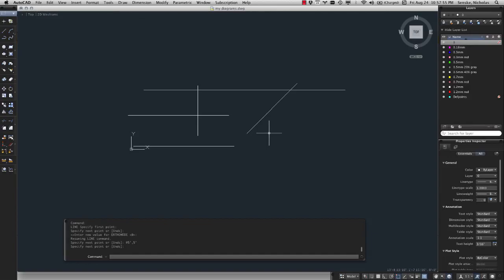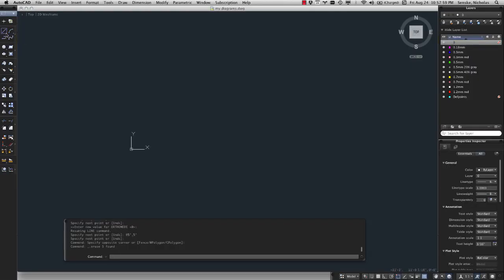So, that's lines. Another thing, too, when you're drawing freehand lines is ortho snap. So I can draw a line, and what if I want to make a straight line? If I hold Shift down, that's actually going to restrict my drawings to 90 degrees and 0 degrees, and any permutation of that. So that's really useful.